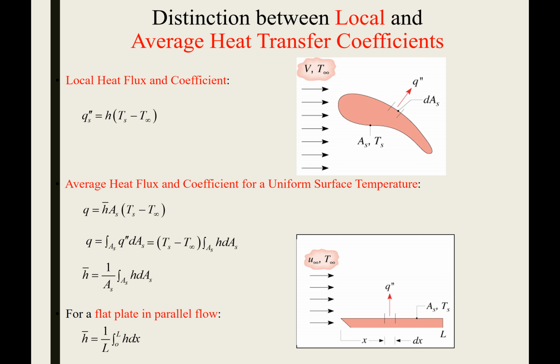So in addition to the convective heat transfer coefficient being dependent on thermal properties of the fluid, there's a difference between a local heat transfer coefficient and a global or average heat transfer coefficient. The local heat flux and temperature can actually vary. If you think back to that example, if I have a really hot surface here and I'm blowing air across, you would expect the temperature in the air to change the further you go down. The air has had longer time to heat up as it goes from x equals 0 down to x equals L. So that tells us we have to start factoring in spatial dependencies.